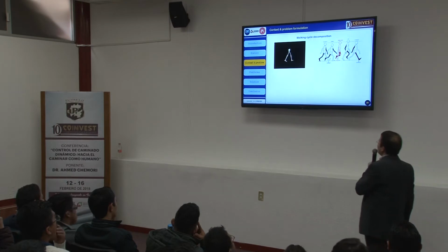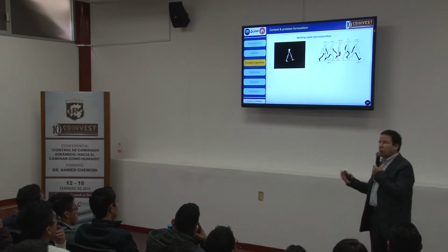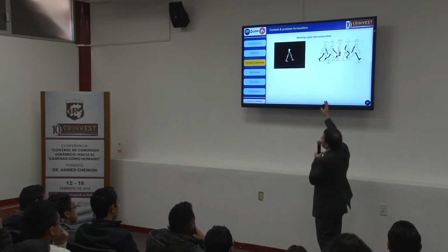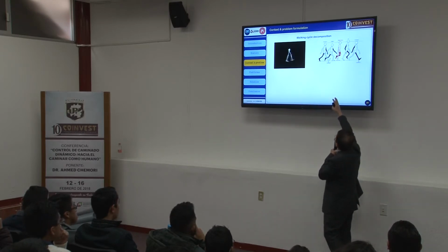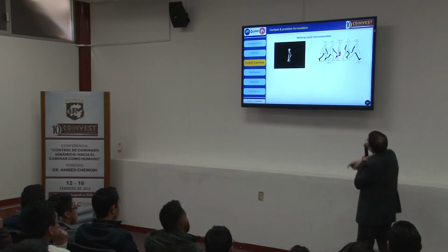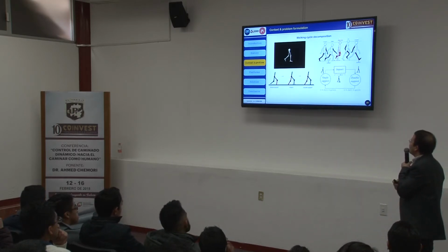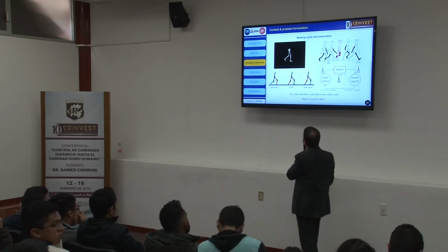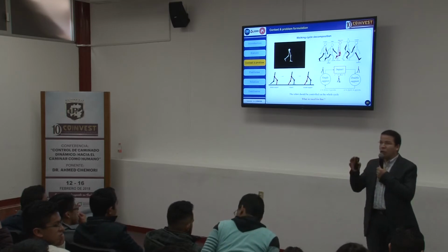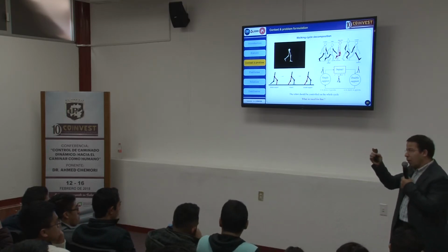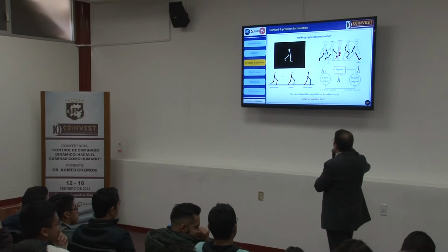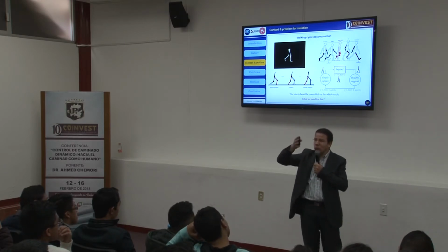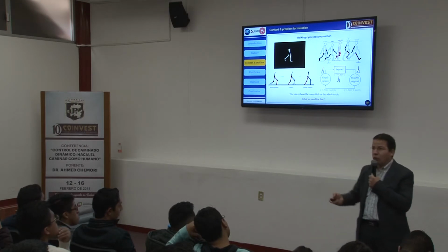Now, as I said before, if you are interested in controlling humanoid walking robots, we have to look at the walking cycle, and the decomposition of the walking cycle is, as I said before, single support, impact, double support, and so on. And now we have to design a controller for the different phases and to keep the stability of the humanoid robot while walking, to avoid falling down. But now the question is what we need to do this task of walking on a humanoid robot.